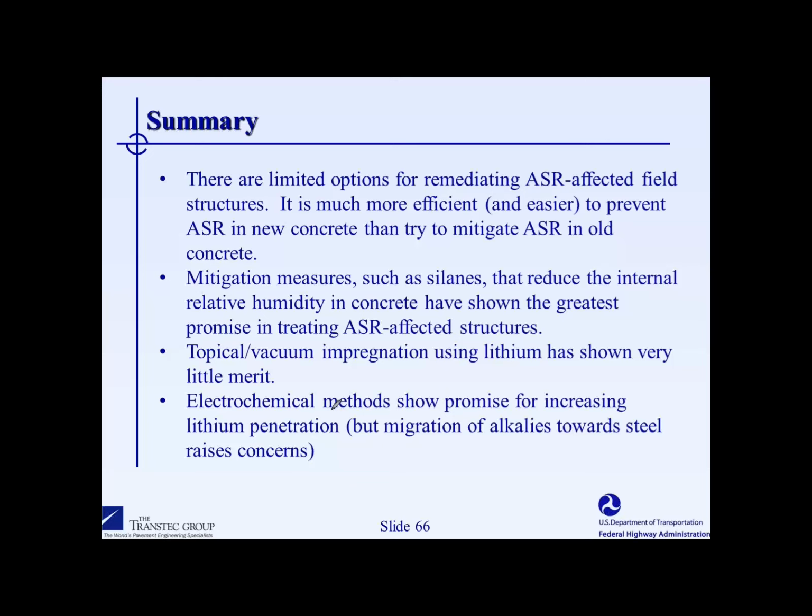Okay, the next question is, what is the application rate of the silane? And again, along with the previous question, how often is treatment required? Generally speaking, and I should say this first, every product has its own recommendation, and we would always refer to the recommendations from the supplier.